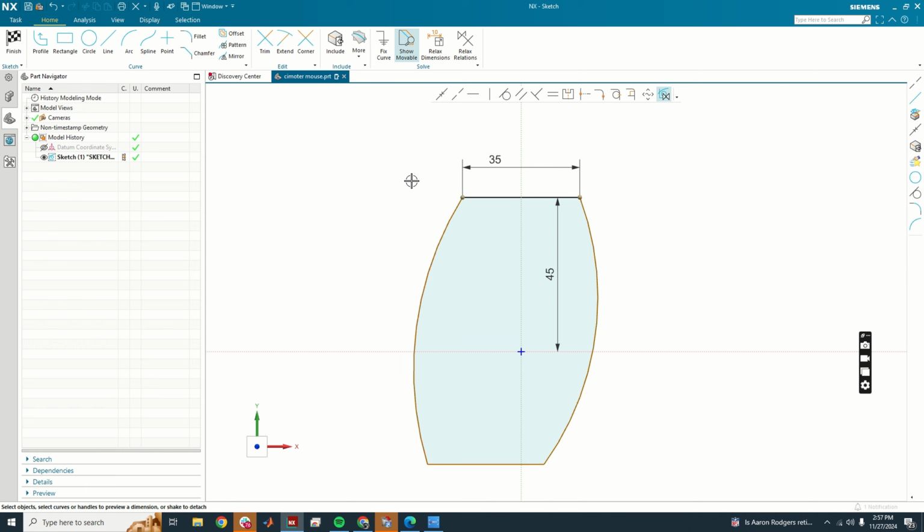It's not showing me, maybe if I try to dimension that. 14, okay, so it didn't actually work. Let me just make sure that this is working, because it is another useful tool to be able to delete relations. So I hover over until I'm there. So the mate is turned red, I select it, and now it's pink. Maybe if I press enter.